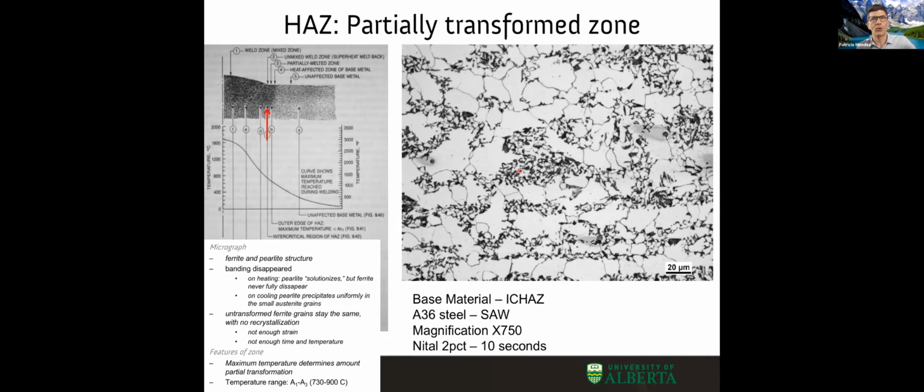And then as we cool down from the CCT, we go from full austenite into whatever microstructure, and what changes is the cooling rate. Now, I never thought of this, but what we would like to do for the heat affected zone is like a CCT that has always the same cooling rate, but different starting temperatures, right? In the end, we don't do it in a dilatometer, we do it in a weld. So similar in many aspects to a CCT, but crucially different in that we start from all different temperatures, while in CCT, we always start from full austenite.